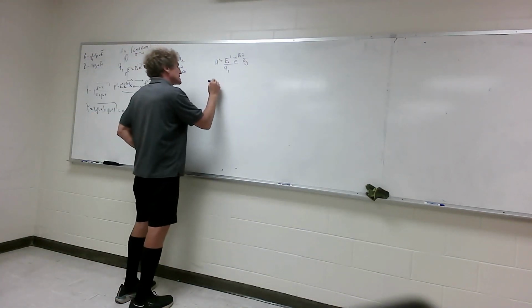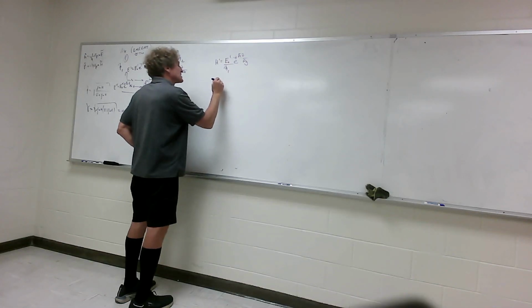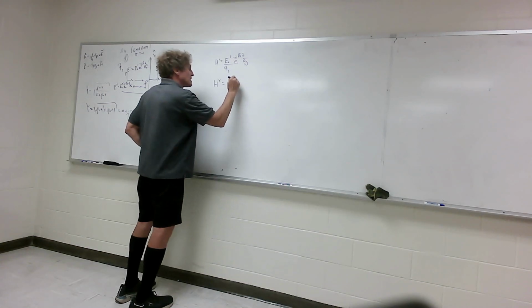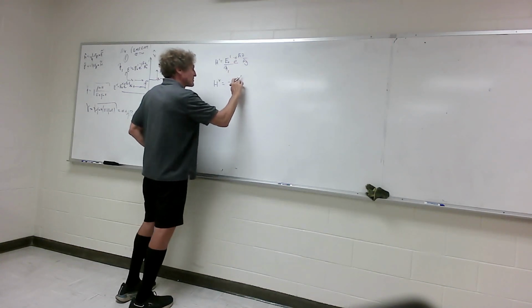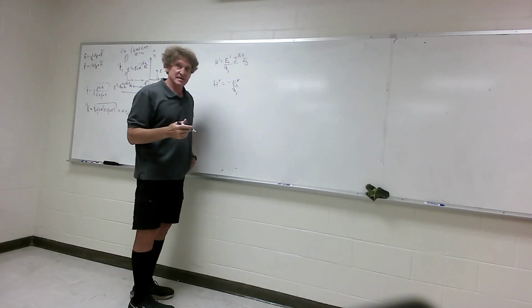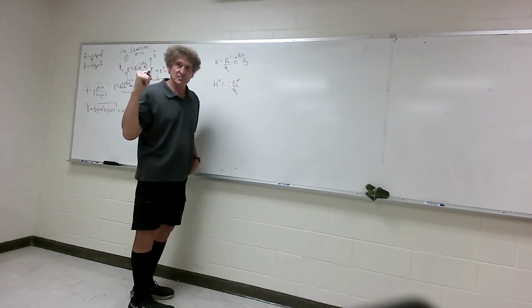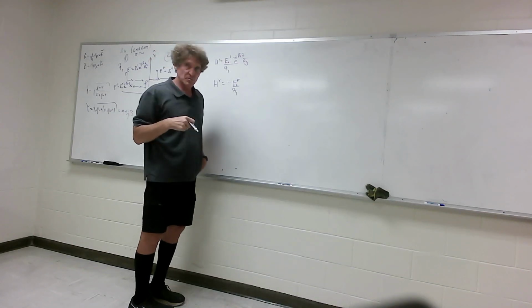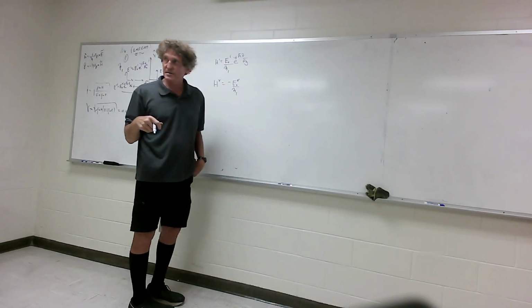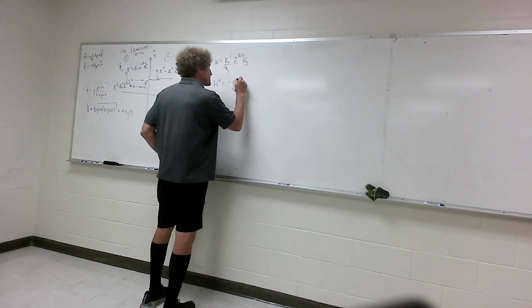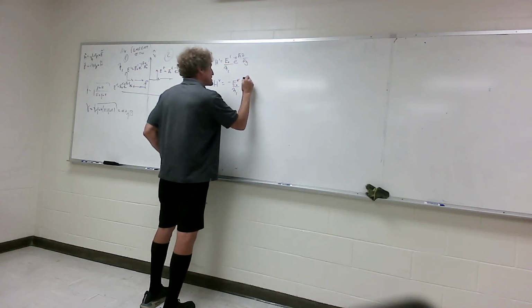And what is H reflected going to be? Well, it's going to be minus E naught reflected, right, over eta 1. Remember the minus sign. E cross H has to be the direction of propagation. If E is vertical and it's reflected, then H has to be into the board, which is minus Y. Correct, class? And this is going to be e to the plus j beta 1 z